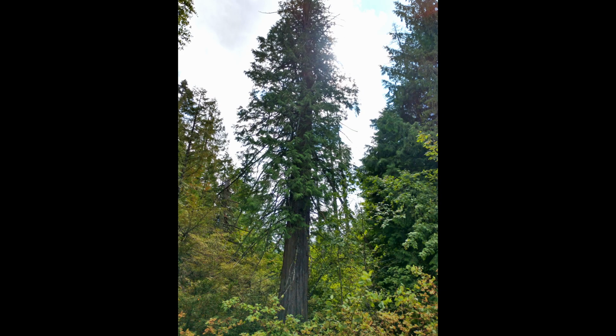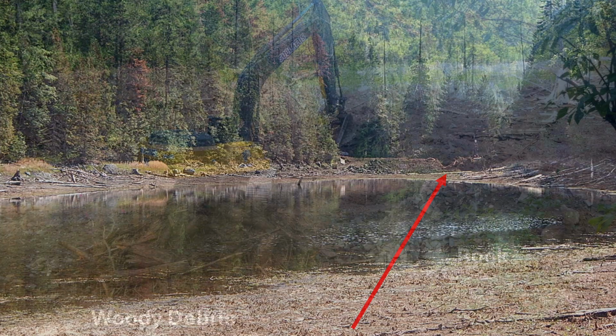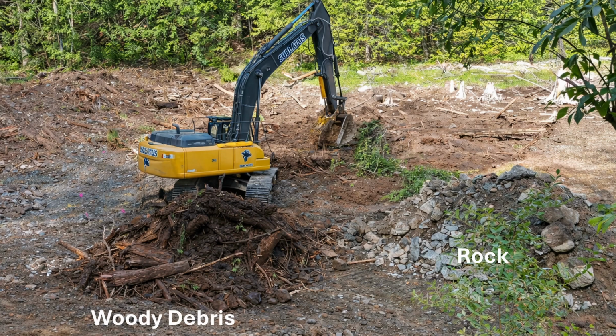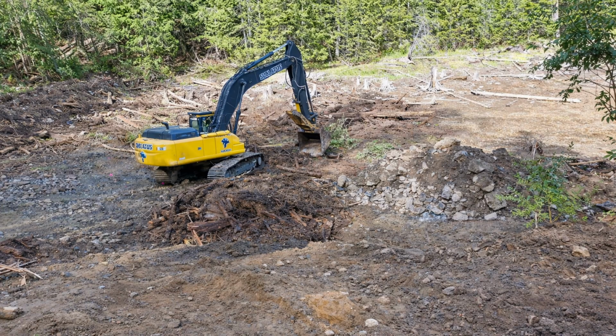We were careful not to damage this old-growth western red cedar tree that was growing near the dam during construction. The red arrow points to where the excavator has begun removing the dam at Violin Lake. Trees and shrubs are removed from the dam and placed in a pile. This woody debris will be spread after the stream and the floodplain are built. The excavator removes soil from the dam and places the soil where the dozer can spread it on the side of the valley. We frequently take elevation readings with the laser level to determine how much soil to remove.